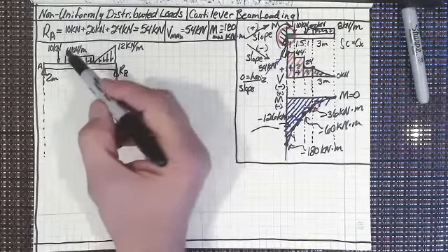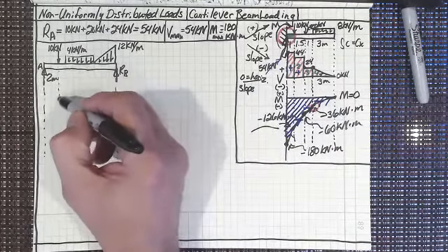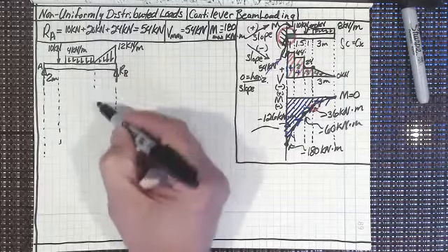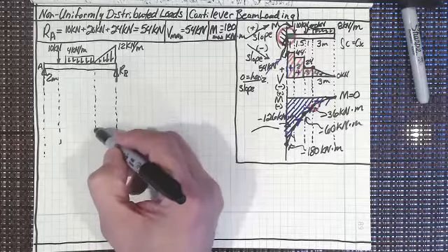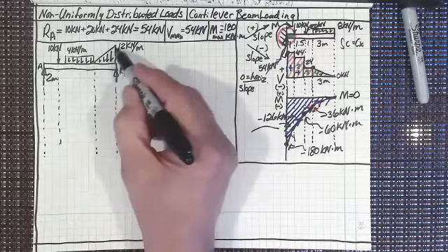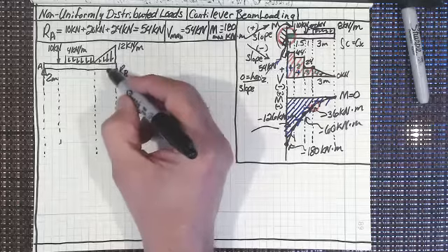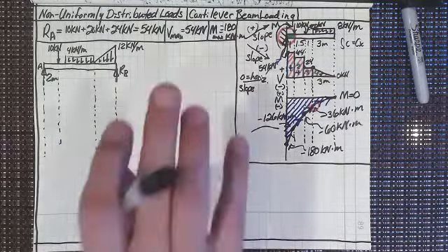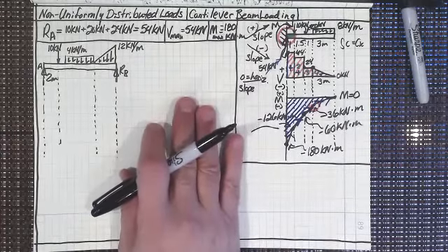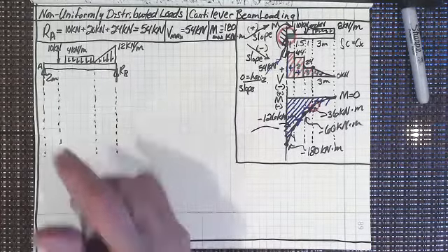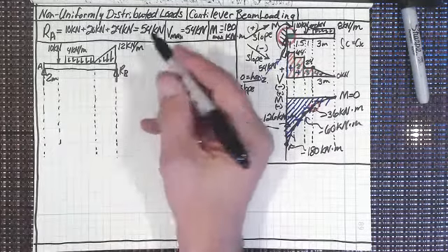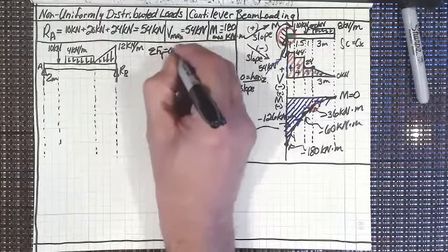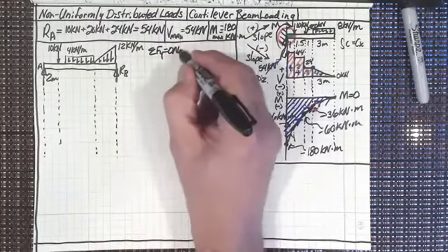And we're going to drop some other lines down here too, some construction lines for our shear force and bending moment diagrams. And this is also going to take into account the centroid for this triangle. Thank God we already looked at centroids, and we know the centroids for triangles and rectangles and everything else. So we can easily do this problem. So the first thing that we want to do, of course, just like always, is sum forces in the y direction.